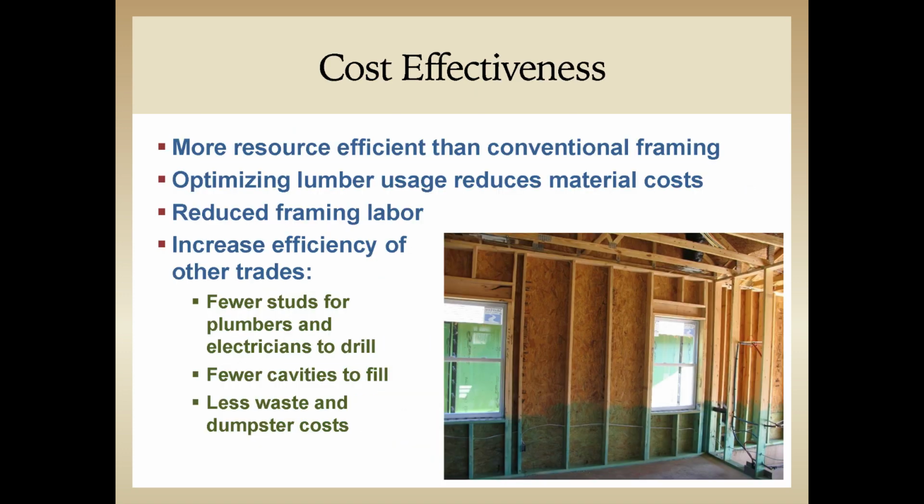Advanced framing is about the only green building concept where real green can actually be put back into your wallet. And that's because it's more resource efficient. You're going to use less lumber. You reduce your framing labor. And then other trades will save time as well, as listed on the slide. And finally, with less waste, there would be lower dumpster costs.